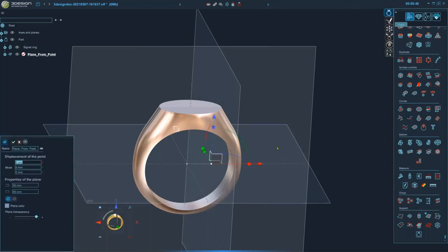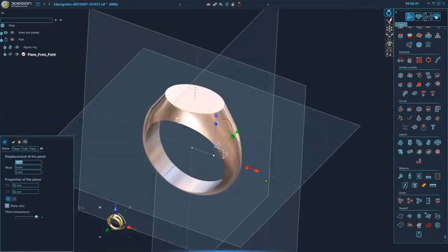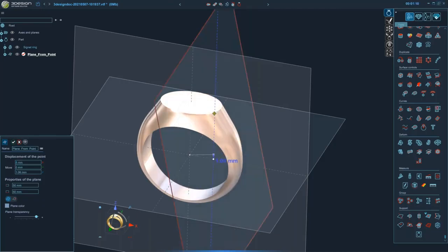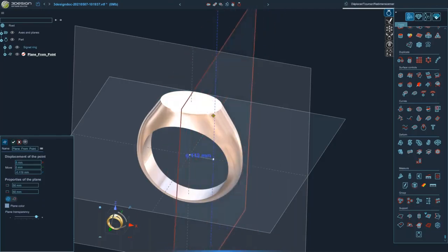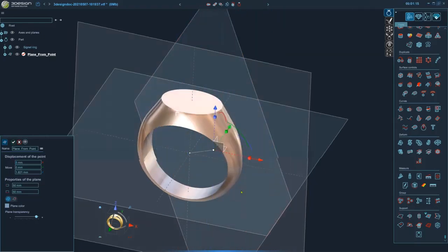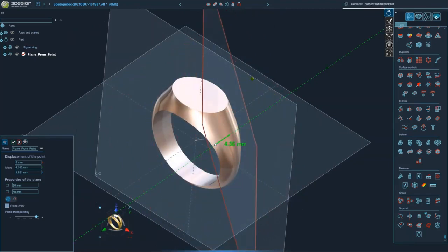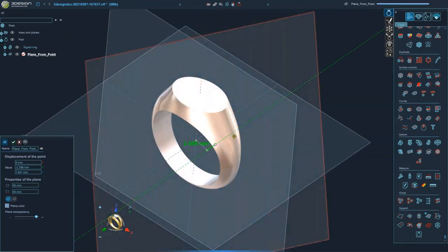It has a gizmo built in here. Unfortunately, with these transform tools, when we include them in a tool like this, just like if we were to use the move, rotate, scale, you're going to have all 3 options: move, rotate, scale. So you not always will use the scale portion. Keep that in mind with some of these tools. So this one, I'm not going to use the scale. It's not really going to affect it much. But I can use the move portion, and I'm not going to use the rotations either, so that I can move this, and you can see that it rotates around that center point.